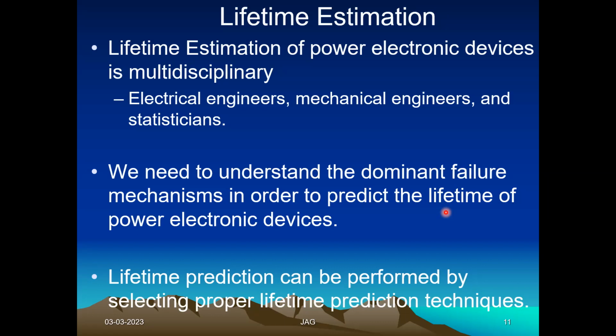The temperature of the IC or the PCB should never be more than the temperature of the surroundings, isn't it? So when the temperature is more, the heat energy from the board, PCB or whatever it may be, will be dissipated to the surrounding area. The mechanism is different. One may use natural cooling without anything, automatically it cools. Another one may use a simple heat sink attached to the semiconductor. Whenever heat is generated, that heat will be carried by the heat sink to the surrounding area.